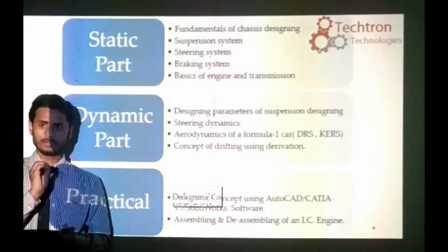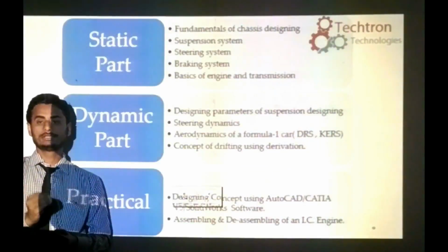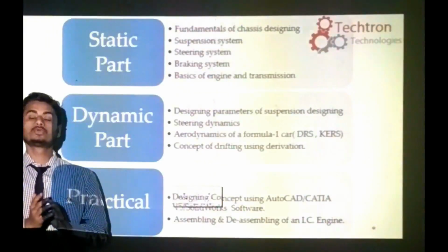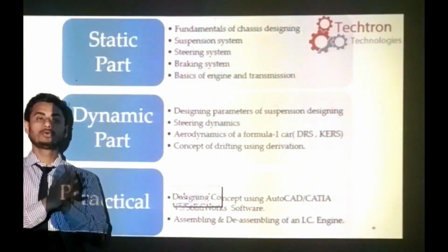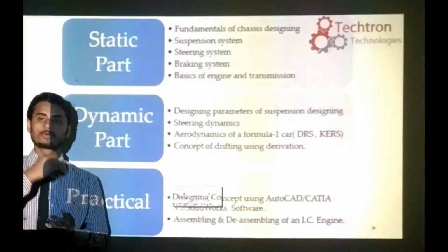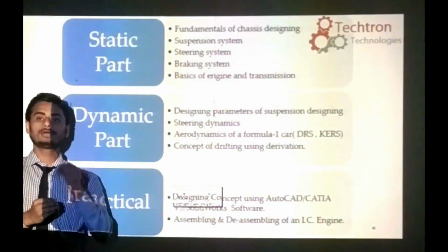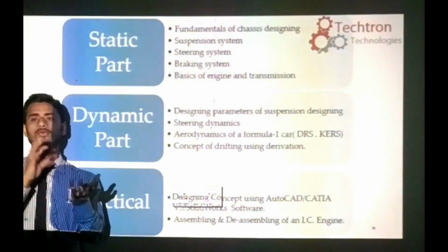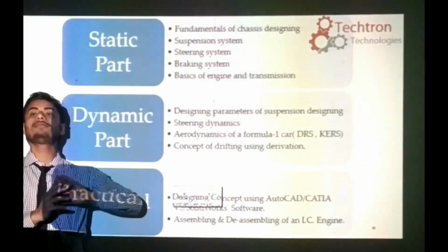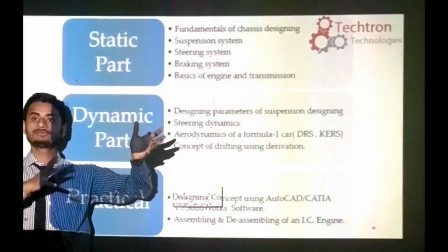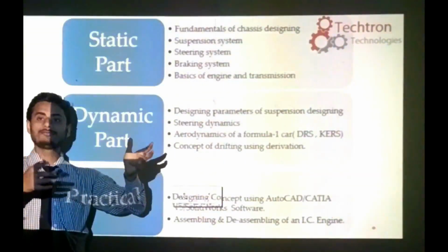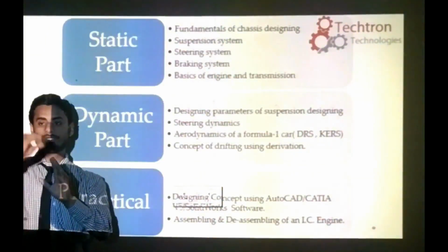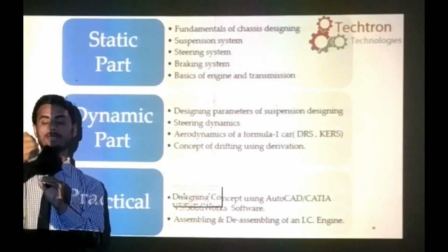As well, trucks and buses carry more loads and more passengers, so we have to go through a different kind of chassis, a stronger chassis. But a sports car or a conventional car has a different kind of chassis. Conventional cars carry somewhat lighter loads and do not have the higher speed of a sports car. For the sports car, we need higher speed, so we have to come up with a different chassis, a different material, and a different aerodynamic design.